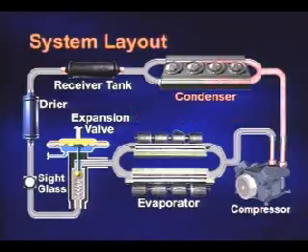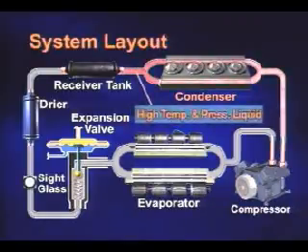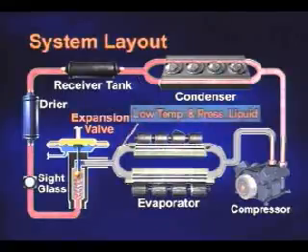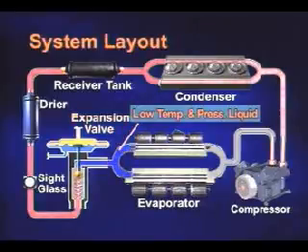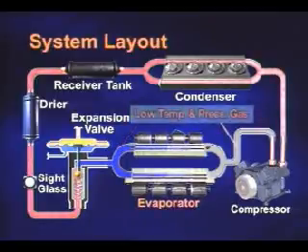The condenser discharges the heat absorbed from the evaporator. Then the refrigerant transforms from gas to liquid. The expansion valve drops the pressure and the temperature of the refrigerant by expanding it to help the refrigerant evaporation. In the evaporator, the refrigerant evaporates from liquid into gas by absorbing the heat energy inside the bus. Then the inside temperature cools down by the evaporation latent heat.